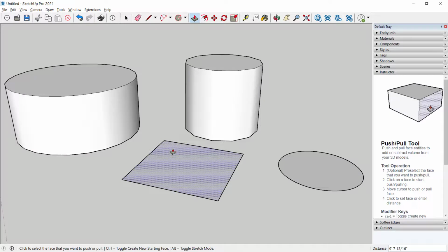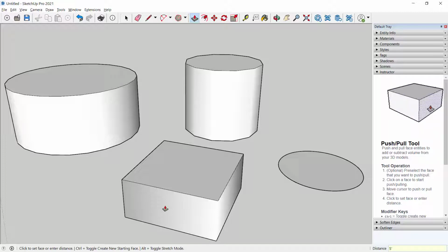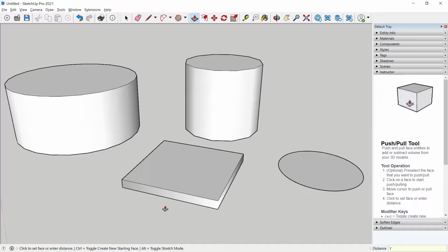And it will basically extrude that surface and make it kind of like Play-Doh squeezed through one of those Play-Doh devices. And you can push-pull up or push-pull down. And you can see down in the bottom here, there is a value in the value box there, the measurements box. If I click a second time, I can also type in 5 feet. And, whoops, I can type in 5 feet if I don't have thick thumbs, and change the value very quickly.